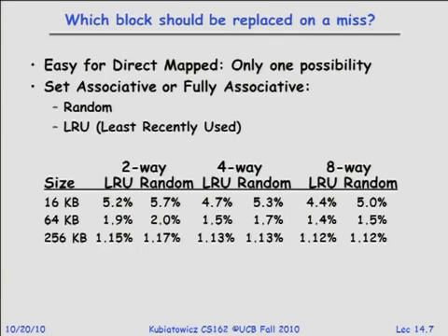What's interesting is that as your cache gets big in hardware, I'm talking about a hardware cache, the difference between LRU and random is almost not worth mentioning, and we're talking about how many misses there are. So this is the miss percentage here. Okay? In fact, if you have a higher associativity in hardware, they often just use random. They have a continually running pseudo-random bit generator, and they grab a random one to kick out.